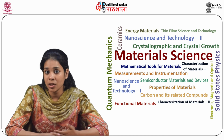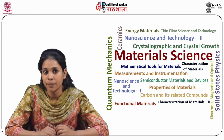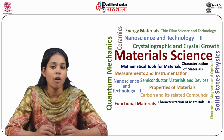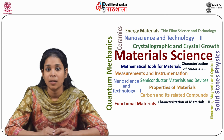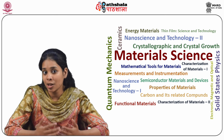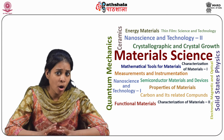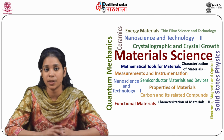So these are some advantages of liquid phase sintering. That is, it produces faster densification due to faster atomic diffusion and due to particle rearrangement. The grain size can be easily controlled. Next, systems which are difficult or impossible to sinter by solid state sintering can be sintered using liquid phase sintering. Moreover, a trace amount of liquid phase is invariably present even in high purity ceramics due to siliceous and other impurities. For example, in silicon nitride, a few angstrom thick layer of yttria silica film is found to always be present at the grain boundaries.